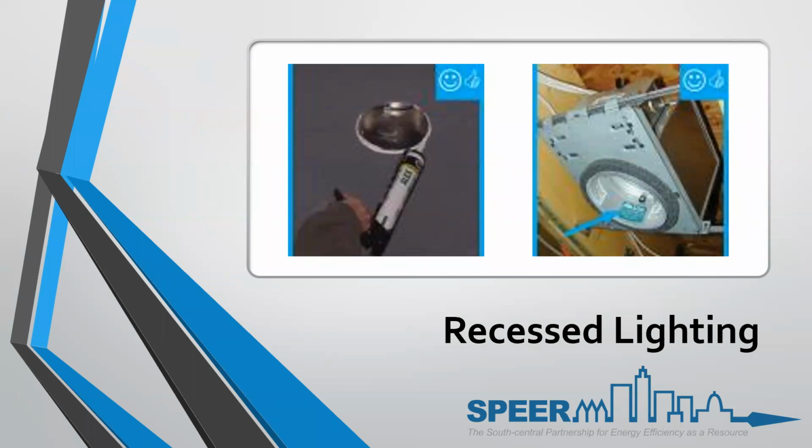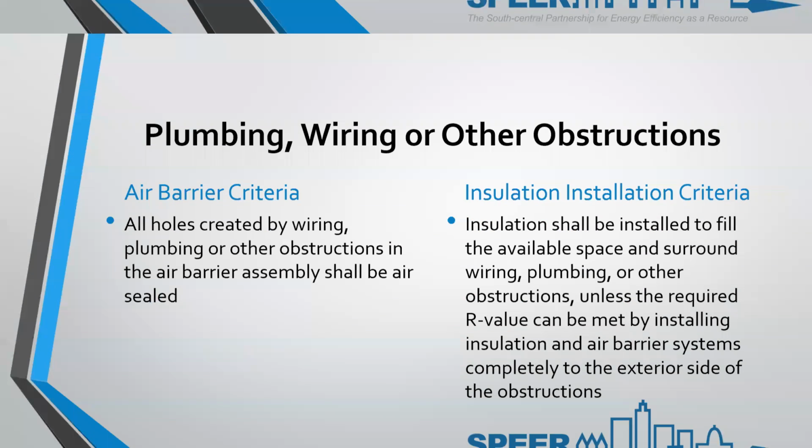A lot of times, if the gaskets are here now at pre-drywall and then you get to final, you don't really know if that still exists. You hope that it does and it wasn't taken down or fallen down, but you have to take the advantage of if it's airtight enough and meets the intent of the blower door ACH, then we're going to make sure that it passes. Due to newer LED fixtures being done, they're more airtight. They have gaskets as well that are pre-installed. This is becoming less and less of an issue with the requirement for this.